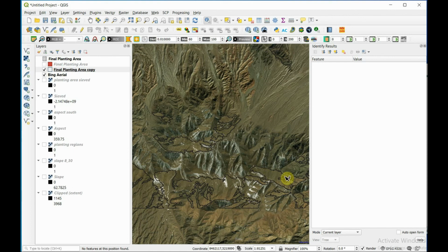And so when we did our calculation to create our planting area, based on slope and aspect, we could also create other rasters first for soil moisture or soil type, and basically create a larger equation where aspect times slope times soil type times water moisture.